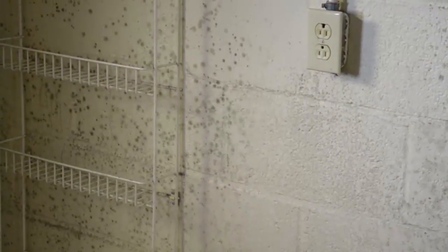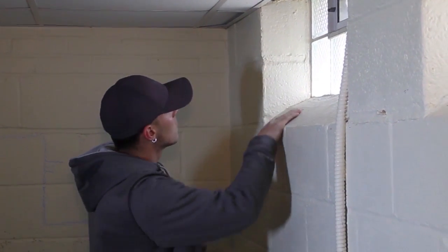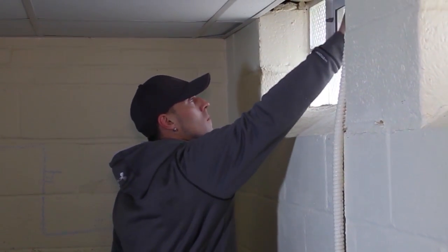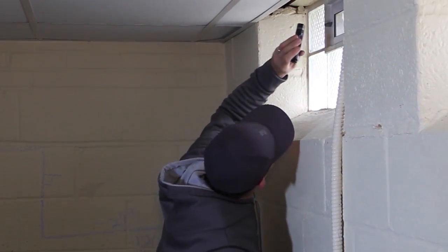Source 14 is lack of circulation or humidity. The property should be checked for proper airflow throughout all levels. This includes turning on appropriate HVAC units, installing a dehumidifier, or installing fans. It is important to note that humidity is rarely a cause of mold by itself. This is usually an indication of some sort of water intrusion.